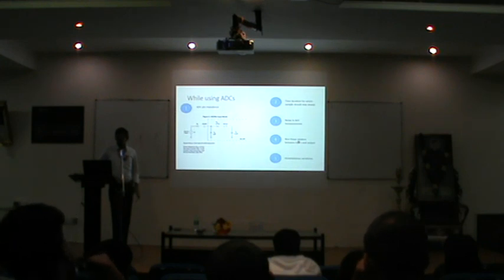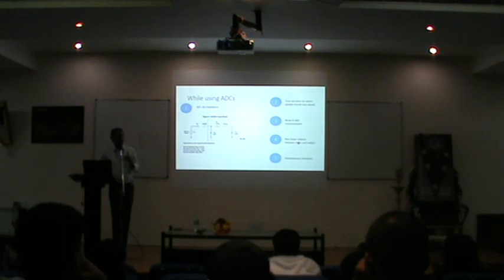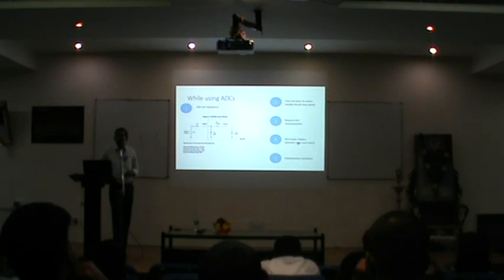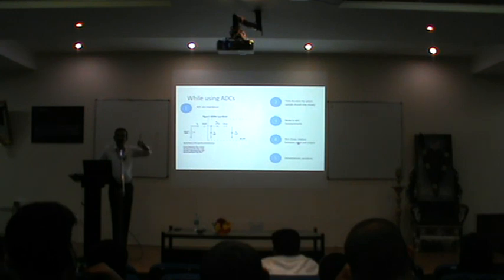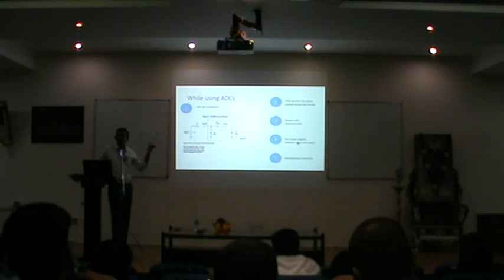And always there will be a non-linear relation, unless you are using signal processing boards, between the input quantity and the output quantity. For instance, if you are measuring a temperature, that is converted to an electrical quantity using a temperature transducer. The relation between these two won't be as smooth as a y equals mx plus c curve. It will be non-linear. You have to account for these non-linearities before you program and control your system properly.